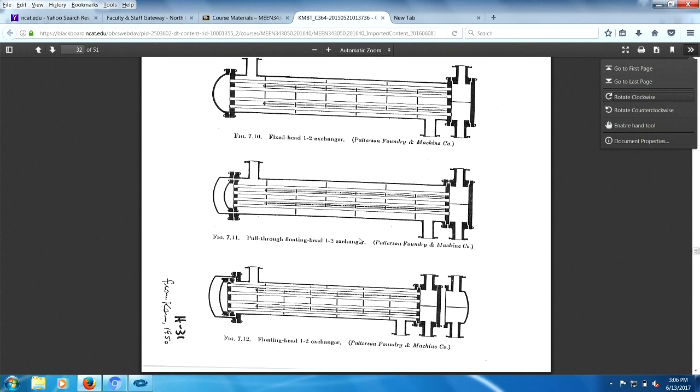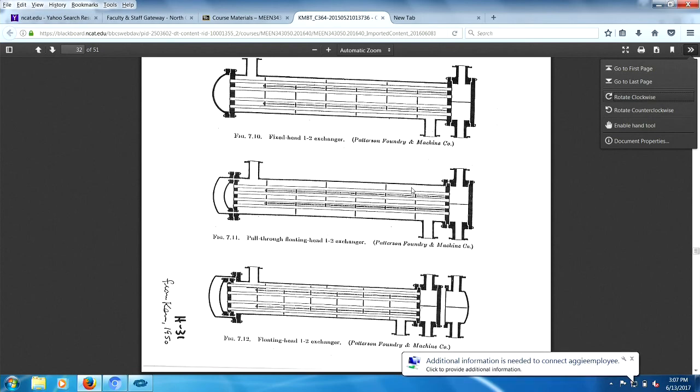Right. Nope, not everything's wonderful here at all because the shell is being wasted. See, this thing's going to cost you $1 million. So you want to try to have it as efficient as possible. So you have this shell volume in here that has no heat transfer surface in it. So you're wasting money here, gang. So then you pop down to this job.